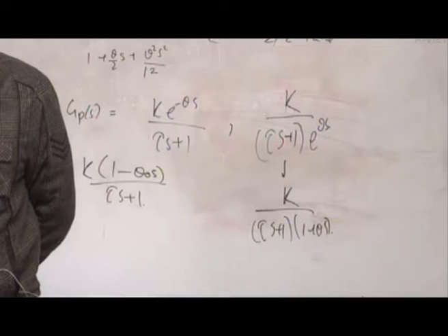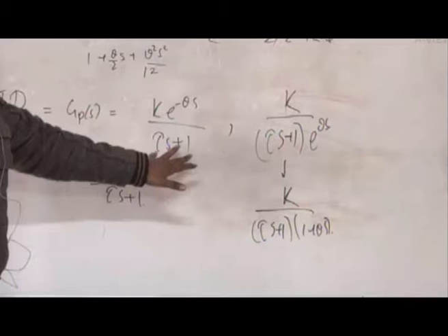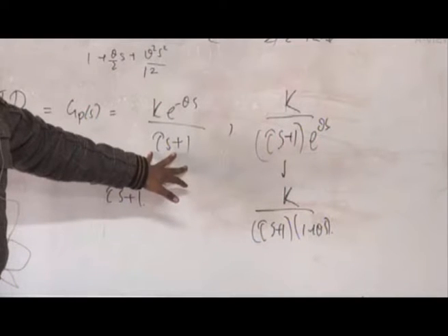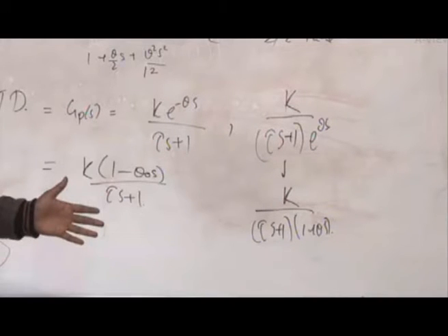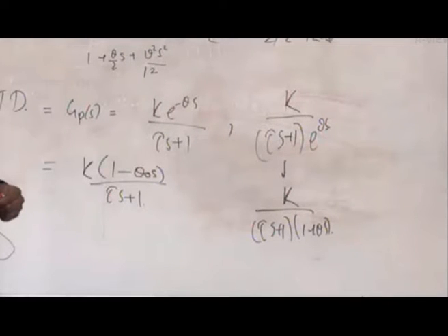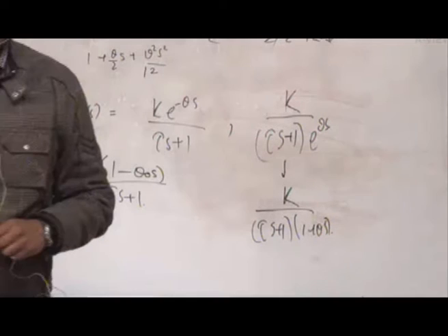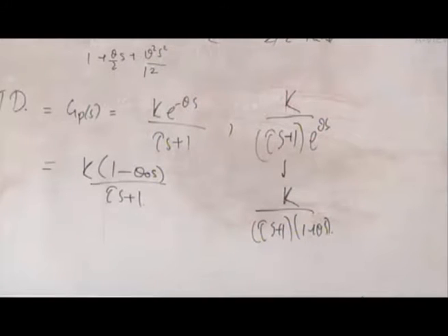By the way, did you notice one thing here, that if you have a first order system, this is already a small or lower order system. Even if we have a higher order system, I can approximate it by this property. So this is also another way to approximate a higher order transfer function in terms of first order plus time delay systems.